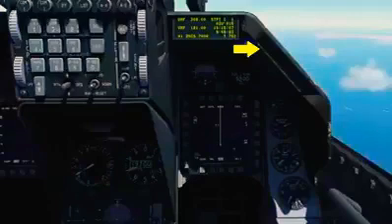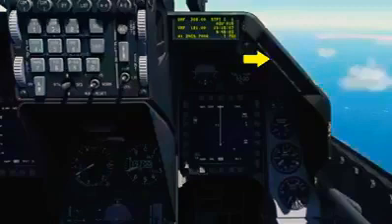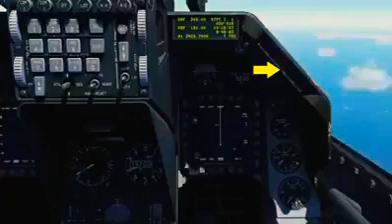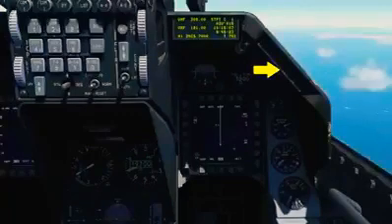The engine fire light will illuminate if fire is detected in the engine bay. Both the hydraulic and oil pressure lights will illuminate if the oil pressure falls below 10 psi for more than 30 seconds, or if either the A or B hydraulic systems is below 1000 psi. The FLCS warning lights illuminate if a malfunction is detected in the FLCS processors, power supplies, input command or sensors, angle of attack, or air data inputs. They will also illuminate if leading edge flaps are locked or the built-in test fails.